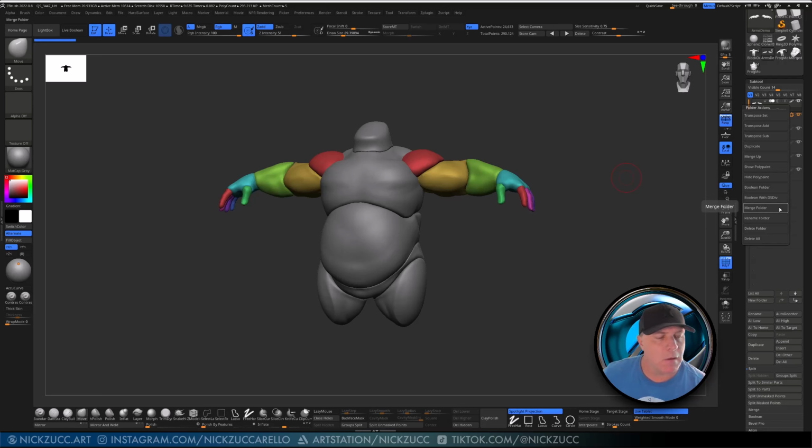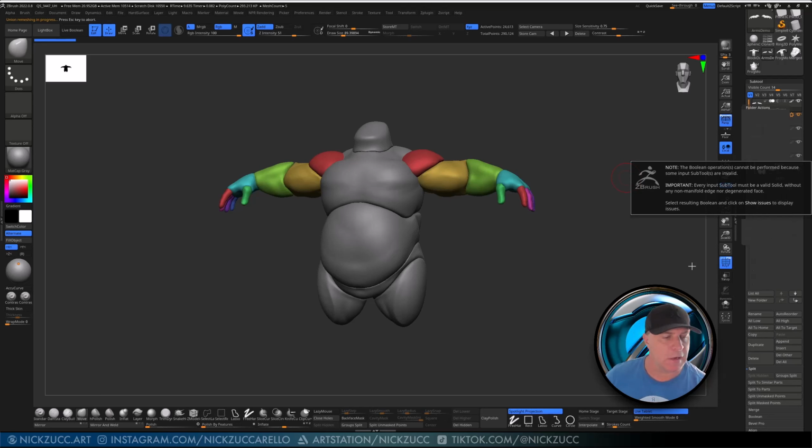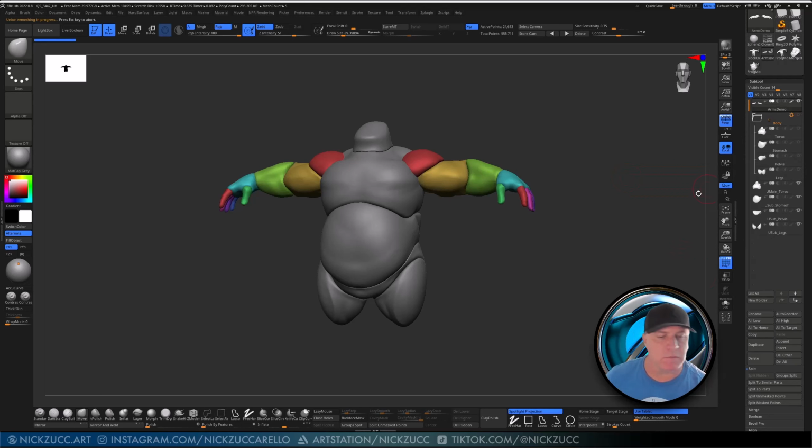It's up to you. Or you can do this Boolean folder. If you do a Boolean folder, it's actually going to take the parts and pieces, fuse them together, and then get rid of the inner parts. So I'm going to use that option. I'm going to say Boolean folder. It'll take a second. It looked like it has some kind of issue on there.